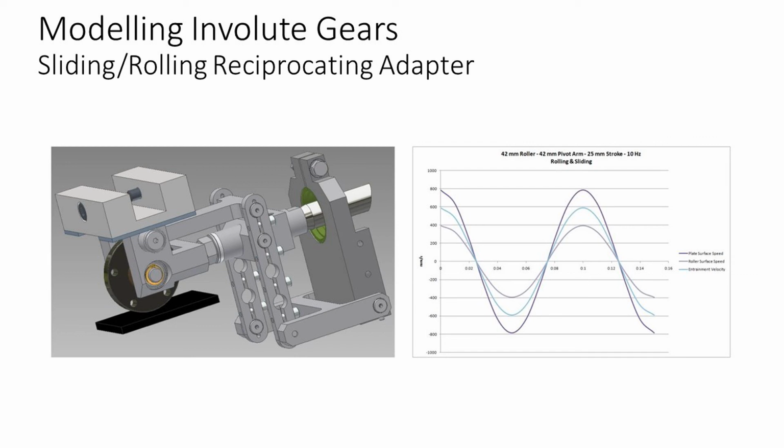The device has not been extensively used for micropitting tests, but has been successfully used as a scuffing screening test for gear oils. In this case, scuffing is precipitated in a controlled way, not by increasing the frictional energy input, but by increasing the contact temperature by electrically heating the plate specimen.